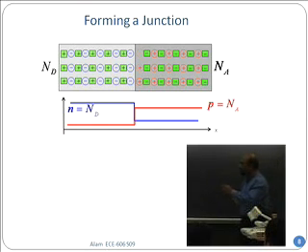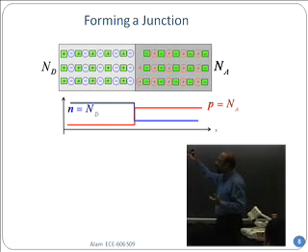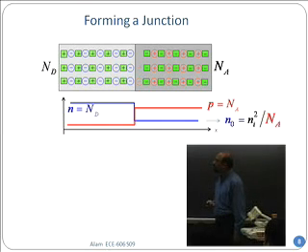Now, when you have this junction and there is a huge number of holes, red holes sitting on the right-hand side, they will not stay like this. What they will try to do is go to the left side, because there are few holes. So this goes. Now, I didn't draw it. I should have just put it on the other side. But you see the other side has so many charges that a few holes crossing over will get diluted in this big region. So I have not drawn that.